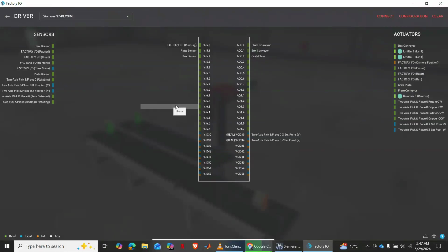The other very important thing I want you to notice here, ukiangalia hapa, is that I have my inputs offset from I5.0 onwards, not I0.0, on the address of the inputs. Why? This is very important on Factory IO kwa sababu before nilitumia address 0.0, 0.1, but then there was a lot of confusion and mismatch, and the system wasn't acting right.